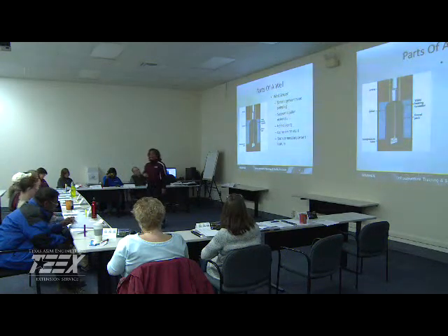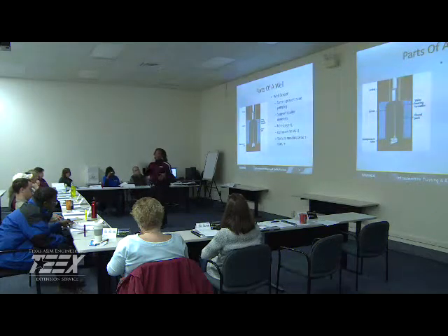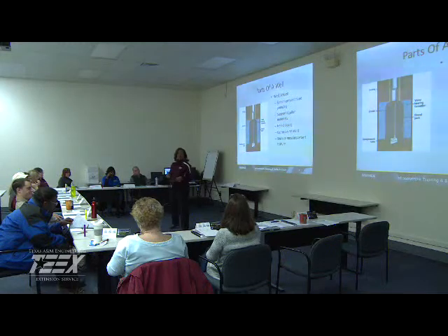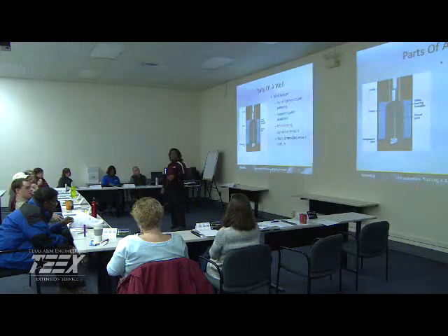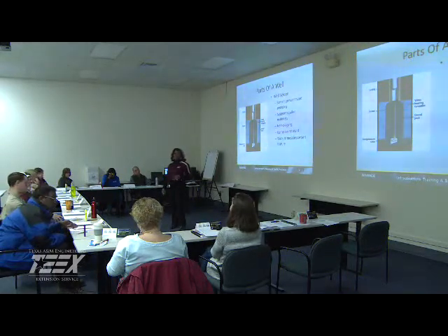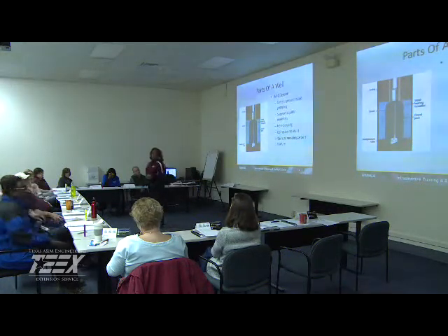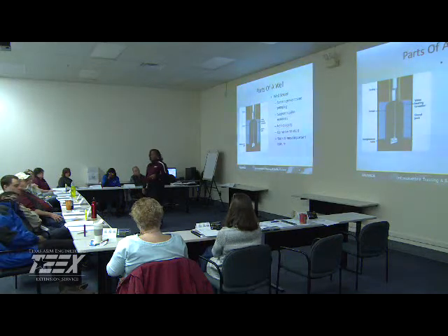Is there a certain percentage of the depth that has to be the screen, or is it always just 10 feet or 20 feet? Now, 10 feet, 20 feet, it just depends on your aquifer. I don't know if those are your standards here as far as your screen. Well, like you say, it is up to the depth of the aquifer, the water formation, but I think they buy it in 10 or 20-foot lengths, so that's what you see most of the time. So they will set it with that section of height to get the most out of what they bought and set it in at a level to get the best use out of it.